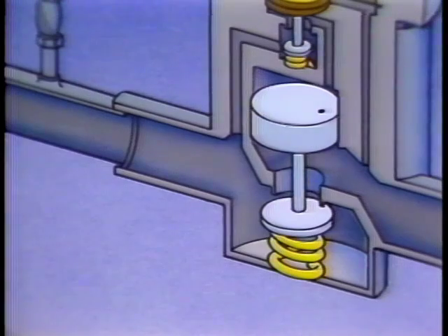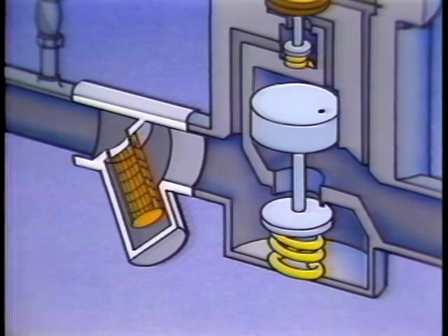Cleaning these devices always requires disassembly. Therefore, care should be taken to provide as clean an operating environment as possible, notably by installing and maintaining an upstream strainer. This leads us to our final variation, the externally piloted valve.